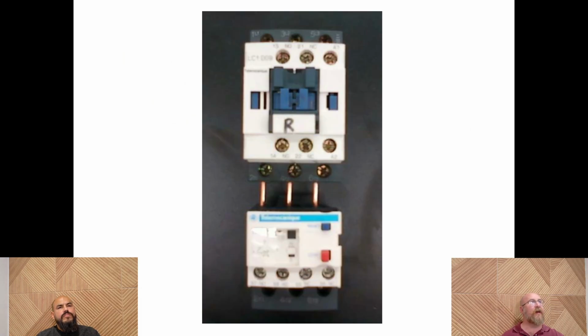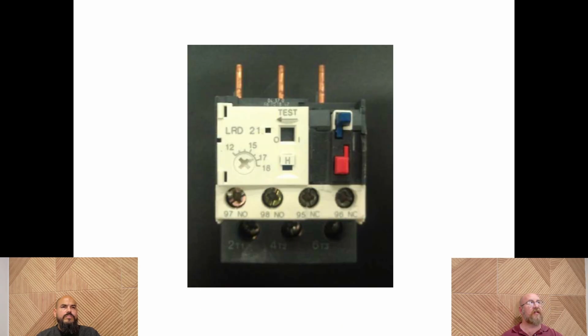Again, these pictures are for you to give you some context, to get you some experience of what you might see out there in the field. This is pretty common. You'll see R and F on two contacts that are both wired essentially into the same thing. Oftentimes that is done so that you swap the legs so that the motor goes in reverse when one contactor's on and the other one is not. And you'll see some more of that later.